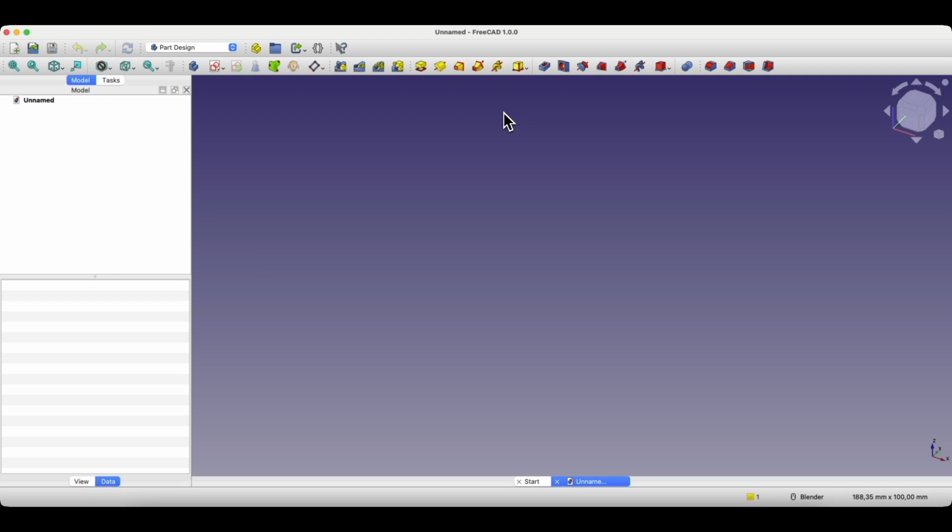We can create such a 3D model in stages. We can make a simple sketch, and based on the simple sketch, we create a solid by extruding the sketch. In the next stages, we can, for example, remove material from this solid. To create a sketch, click the Create Sketch icon,